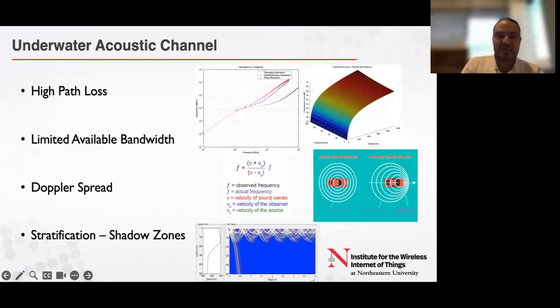So at most times you're looking at a few tens or few hundreds of kilohertz of bandwidth. And if you're very, very lucky, and you're very short in distance and there's a super isolated environment, then you're getting a few megahertz of bandwidth in this domain. Compared to standard Wi-Fi, which is around 20 megahertz in 2.4 gigahertz Wi-Fi, it is really, really slow.